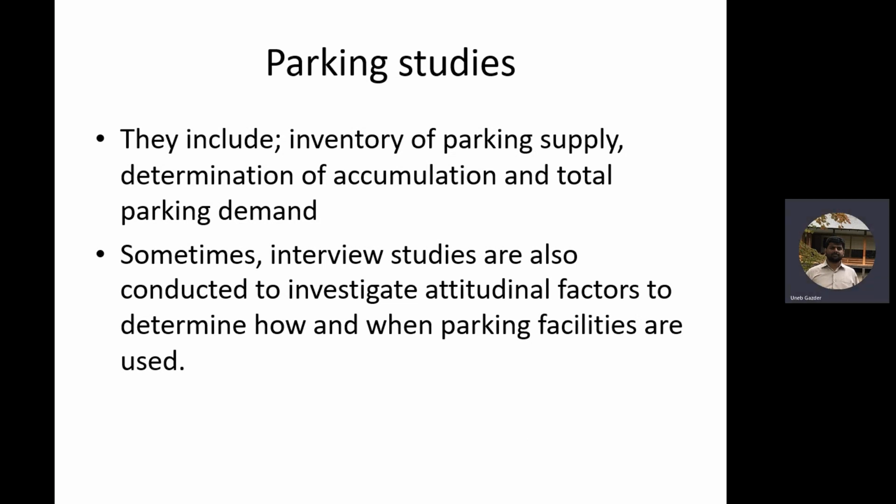So why? Because we don't have enough parking spaces? No, we have. But the accumulation is very high. If these vehicles were coming in different hours, parking area was enough. Okay, so problem of accumulation. Too many vehicles at the same time. Okay, so these three things are important for any parking study.